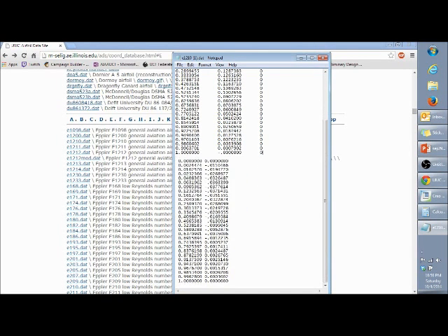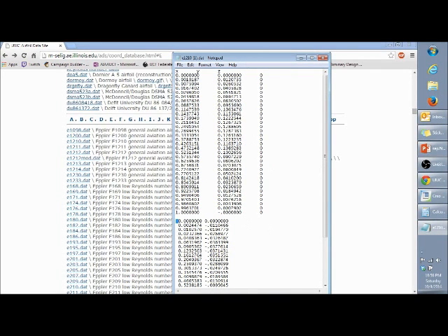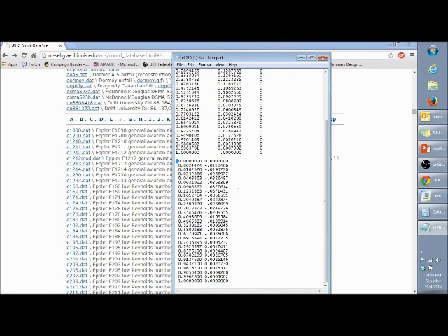And you'll want to do the same for these. For the record, this represents the upper half of the curve of your airfoil, and this represents the lower half. It does take a while to make sure all this stuff sets up, but all these steps are very important, because like I said, Pro E will freak out if you don't do these steps.